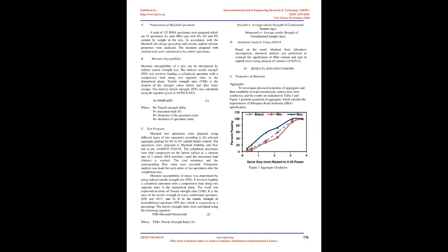Volumetric properties of HMA are necessary requirements to ensure good performance, and these properties are directly influenced by the mix grading, aggregates surface characteristics and compaction energy. Asphalt mixes prepared with 6%, 9%, and 12% hydrated lime, Portland cement, limestone and silica fillers resulted in decreased VMA and VFA as the filler content increases, and the optimum asphalt binder content increases as the filler content increases. Type and content of filler can affect volumetric properties of asphalt mixes.